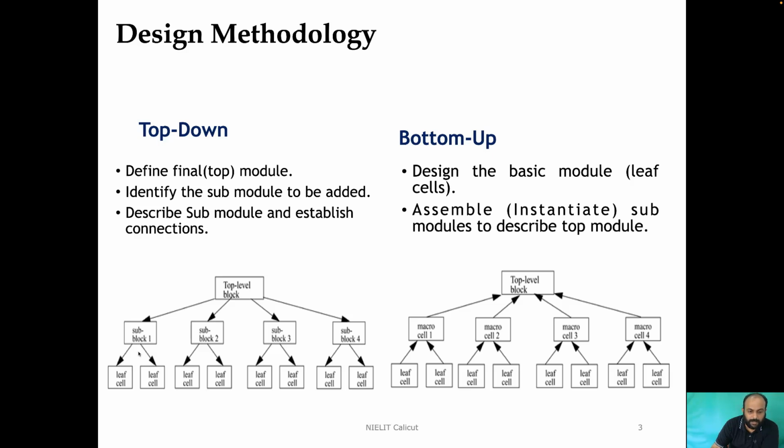For example, when we are designing a processor, we will first describe the processor IOs, then we will describe a data path unit as well as a control unit that support the instruction set architecture. Then within the data path unit we will decide what kind of ALU should be going in, what kind of adders will be going in, what kind of registers will be going in, and so on. So that comprises the top-down approach.